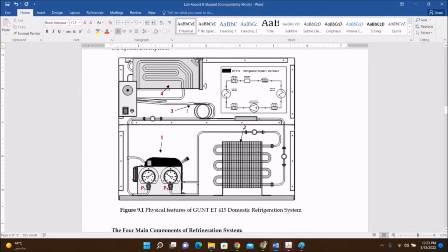Here the condenser and compressor are at high pressure, so they are kept outside. The evaporator is at low pressure, so it is kept inside the room, and the condenser and compressor outside the room. Then it is called a split air conditioner, mainly to avoid noise. The compressor and condenser are kept outside in the atmosphere, and the evaporator is kept in the space or room.